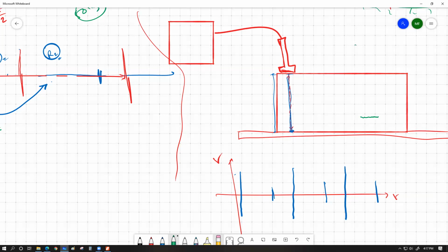Whenever we bring the probe right over here, the ultrasound pulses are going to reflect off this crack's top surface and eventually go back to the probe. It is not going to travel through the crack and eventually rise up. And this would take a significantly smaller time. The part that I need you to understand is that the time it takes for the ultrasound pulse to travel all the way through the thickness and eventually go all the way up would be longer.